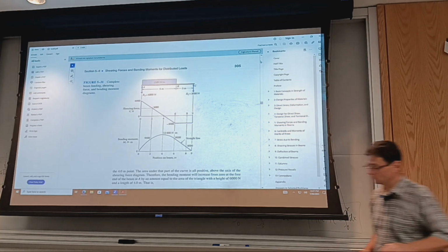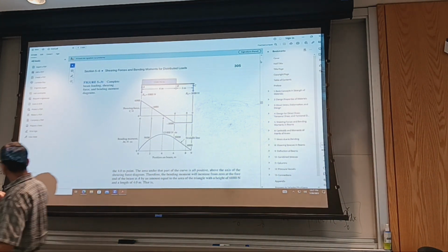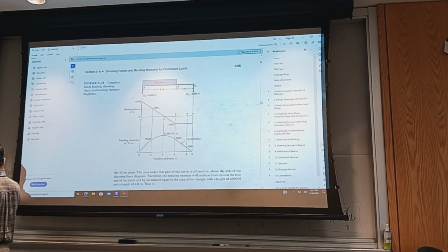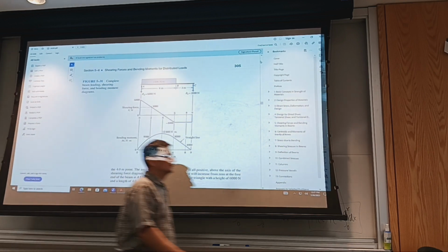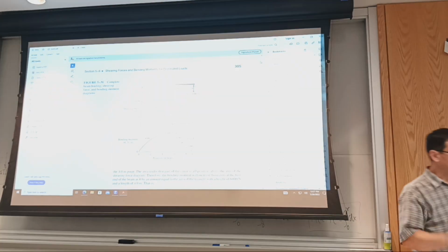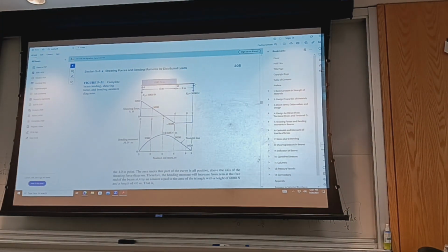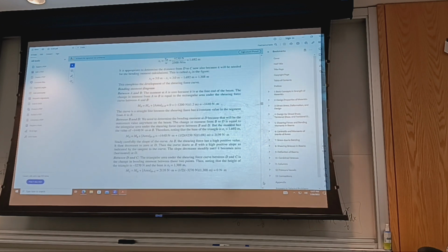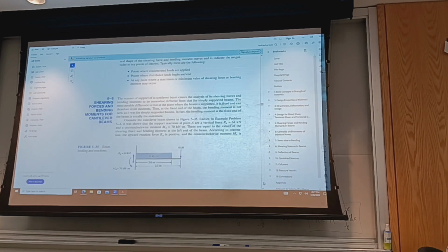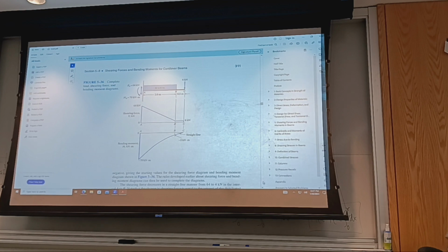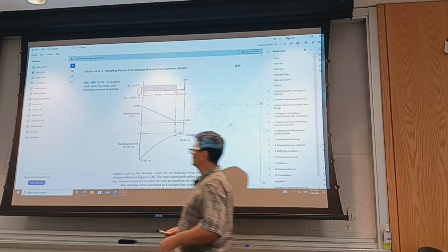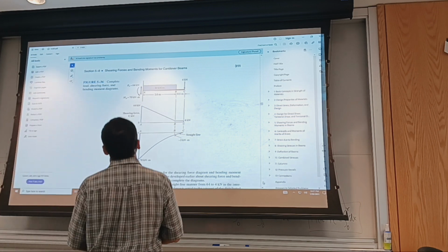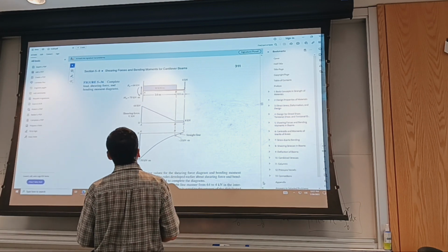I told you, for shafts having pulleys or hubs attached to them, a parabolic shape of the force spread over the length of the hub is a better modeling of that loading. So again, the method of 3 moments, we're not going to discuss it. That's for statically indeterminate beams. For our problem, we can use deflection and the tables at the back of the book to solve the same problem.